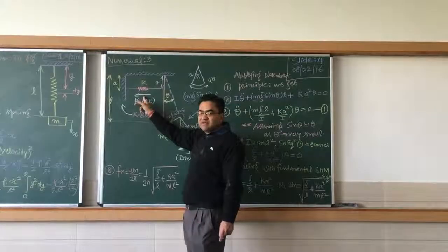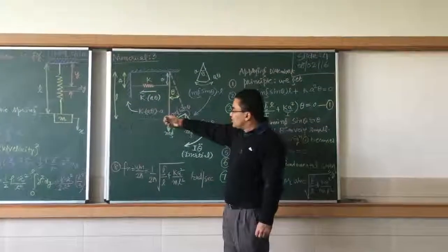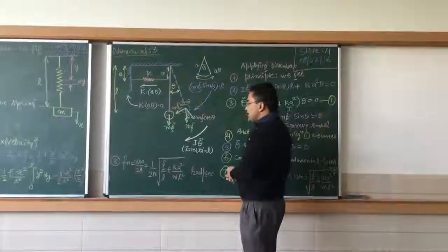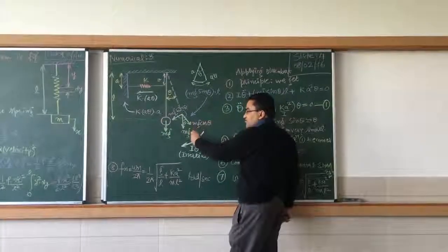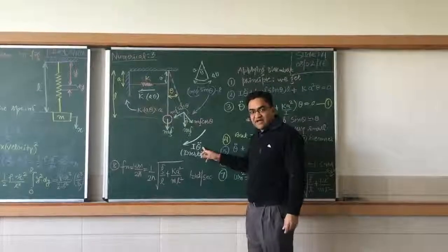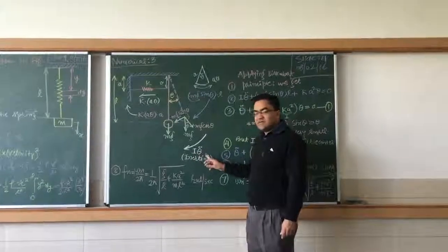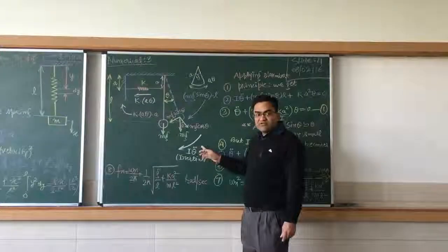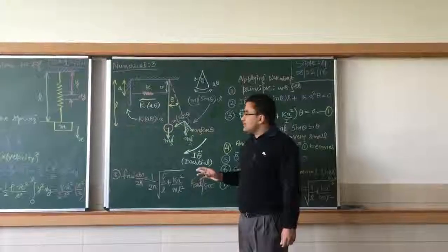Obviously it is in the opposite direction to the motion. The direction of the motion was on the right side. I had kept my hand on the ball and pulled it in a right direction to an angle of theta. Now, since the ball is in rotary motion and traveling an angle of theta, an inertial force due to the D'Alembert force comes into the picture. That will be given by moment of inertia multiplied by the angular acceleration, that is I into theta double dot. This is an inertial torque provided due to the D'Alembert principle, which will try to bring back the system to the equilibrium condition.